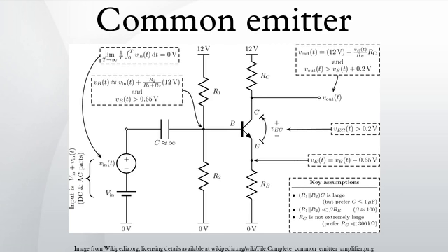One common way of alleviating these issues is with the use of negative feedback, which is usually implemented with emitter degeneration. Emitter degeneration refers to the addition of a small resistor between the emitter and the common signal source. This impedance reduces the overall transconductance of the circuit by a factor, which makes the voltage gain. The voltage gain depends almost exclusively on the ratio of the resistors rather than the transistor's intrinsic and unpredictable characteristics. The distortion and stability characteristics of the circuit are thus improved at the expense of a reduction in gain.